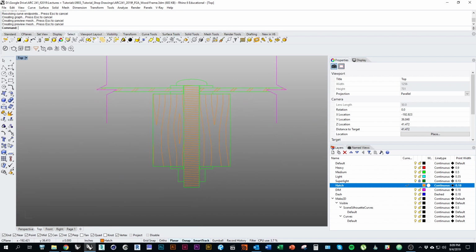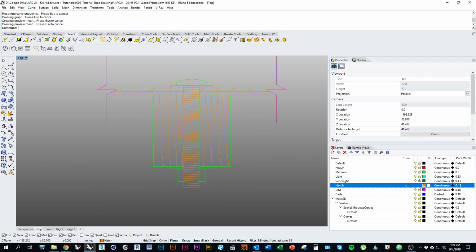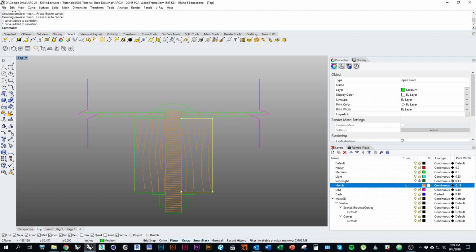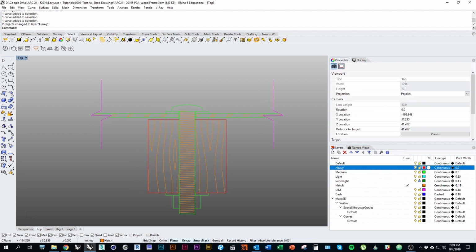Okay, and then the last thing I could do is, if I want to, I'm going to go ahead in here, and actually, before I line weight this, just because I think at this scale we may be looking at drawings where if those lines are too close together, a double line will show up as a solid line. So what I would actually do here is lay it out on my page first, and then mess with the line weights and make sure it's reading properly.